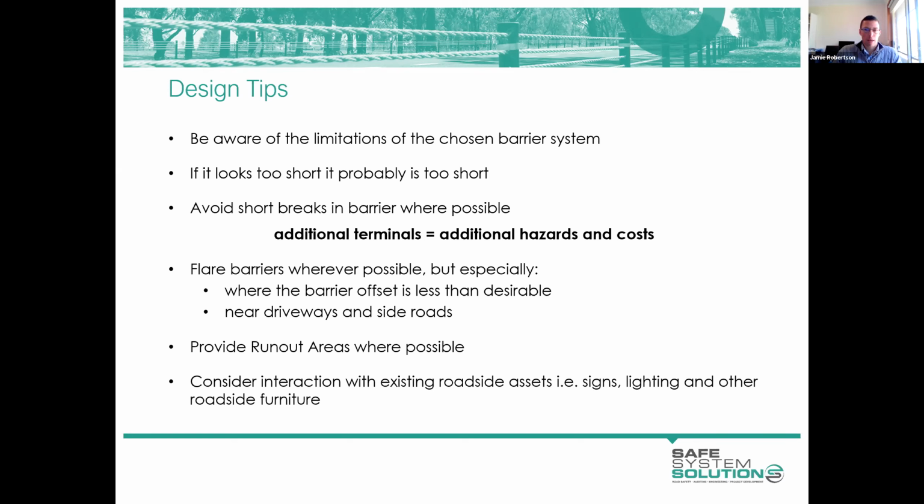You can't gather enough information on site and through other means before you start designing a barrier. So get out there and think about all those pieces of roadside furniture that might be impacted or need to be relocated. Do a dial before you dig. Be mindful of services before you get out there, and then look for the telltale signs when you're out there.